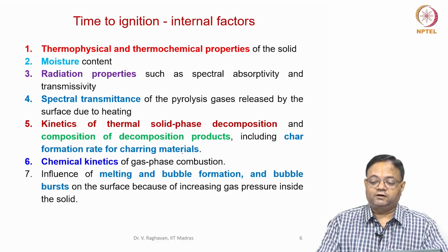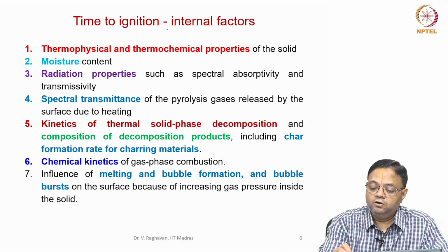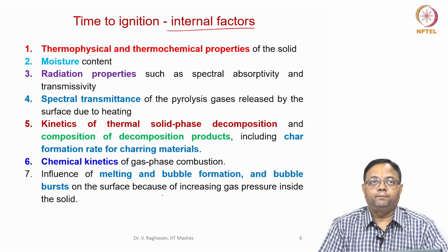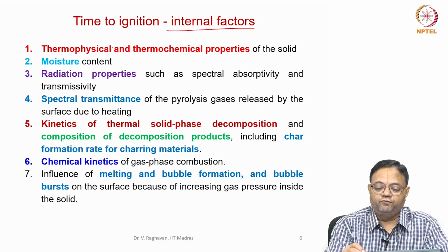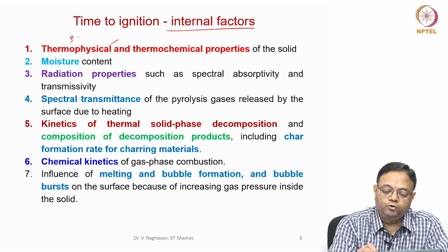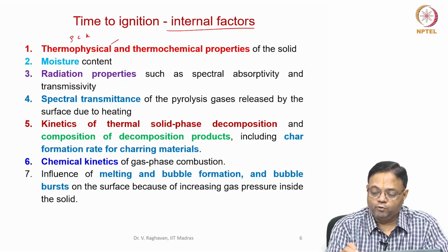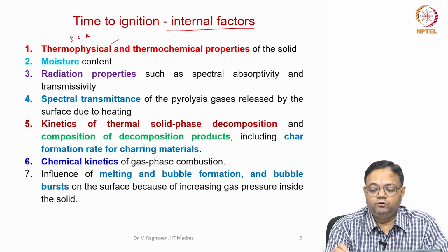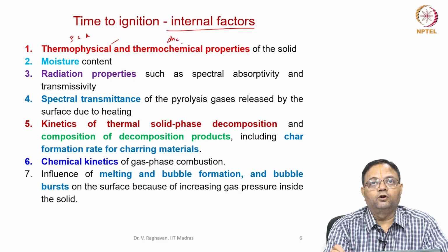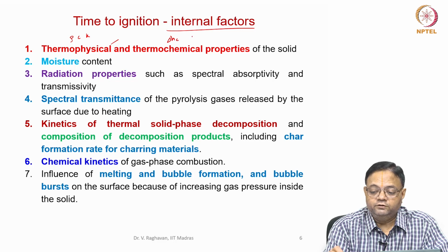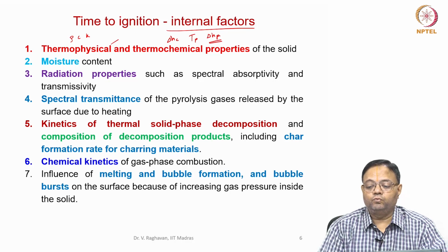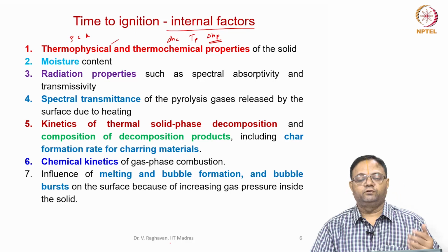What are the internal factors which will affect the time to ignition? Thermophysical properties: rho, C, K, etc. Thermochemical properties: what is the calorific value? Then the pyrolysis temperature and heat of pyrolysis, one more characteristic which will come into play. So these can be these.